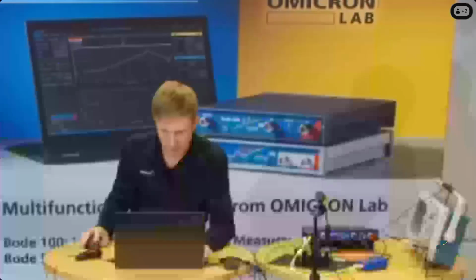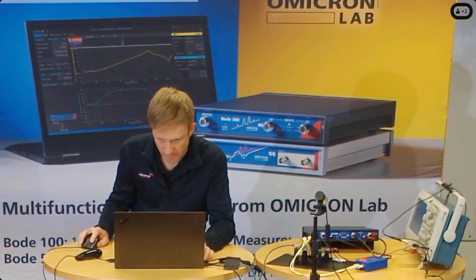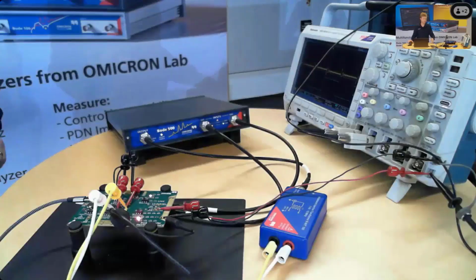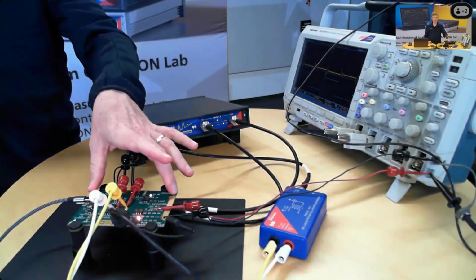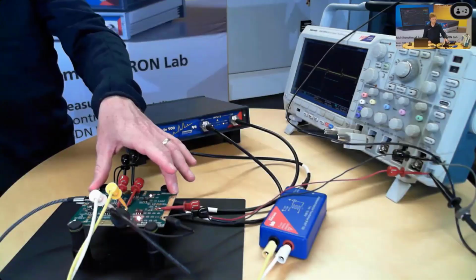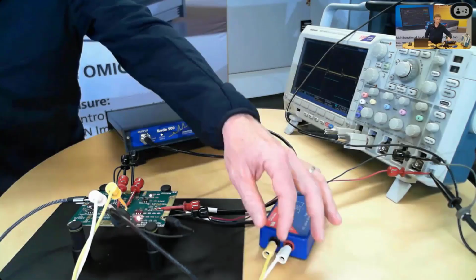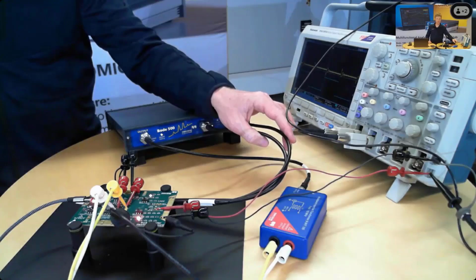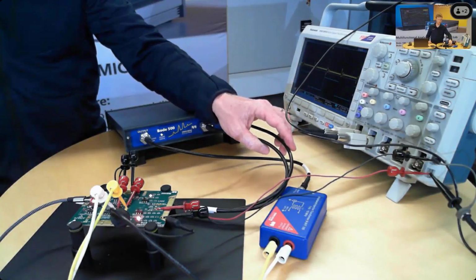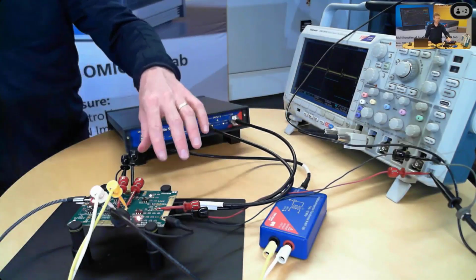First, I'm gonna stop my share and try to share my setup with you. So that's the setup. I have the Bode 500 here. This is the device under test, our test board. Then I have the injection transformer here to inject the signal into the feedback network. Then the channel 1 and channel 2 connection. Since the voltage is so low, I just use a direct one-to-one connection with some test clips. Don't even need a special probe.